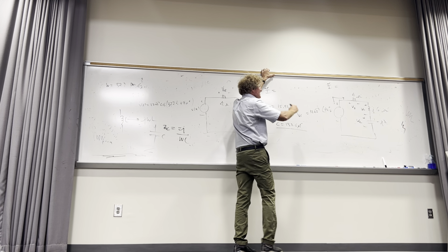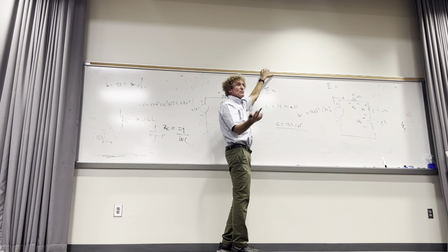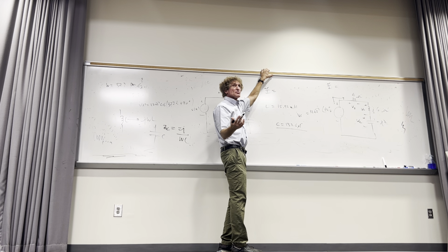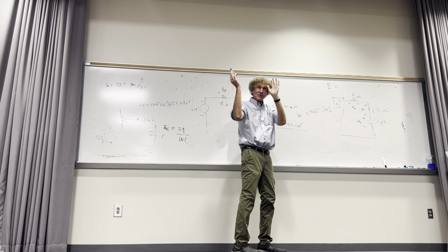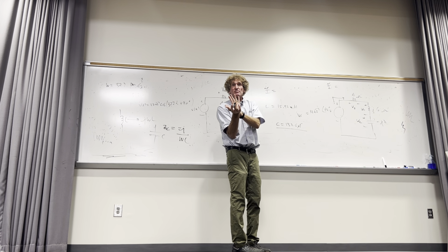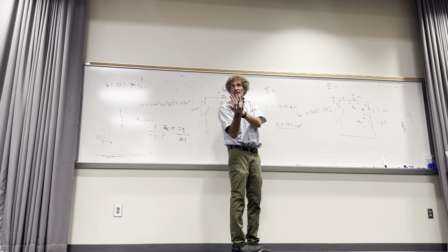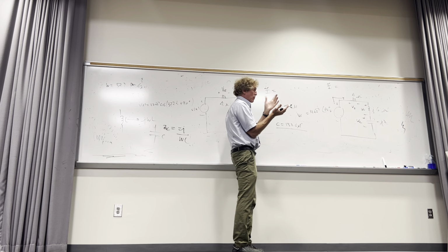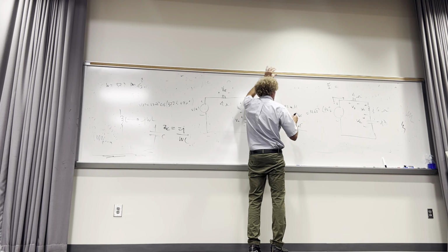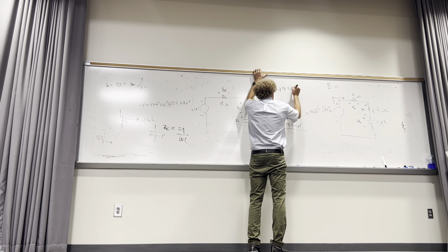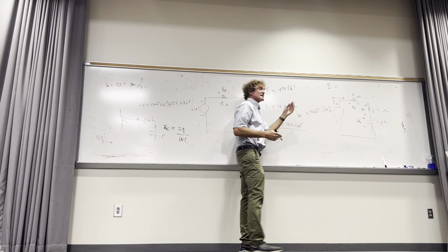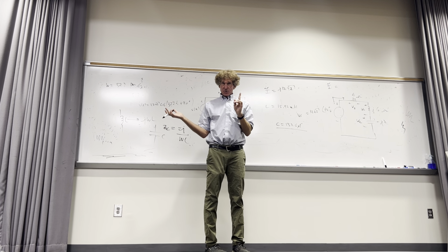So the voltage is this. Now you can put that in any way you want, but guess what? You can also put J 12 times square root of 2, because that's what an angle of 90 degrees means. It just means J. Y'all with me, class? Or in polar form, that would be 12 square root of 2 at 90. So this is going to be J 12 square root of 2. The J is the same thing as an angle of 90 degrees. You all hear me on this?